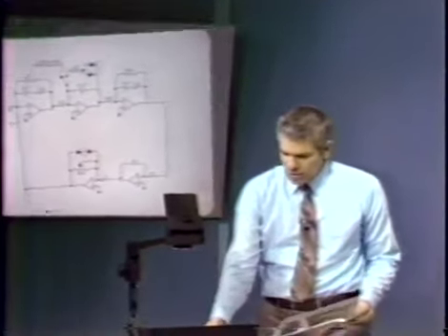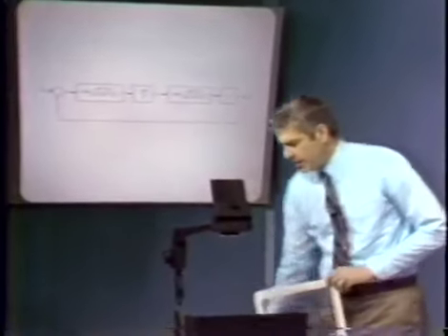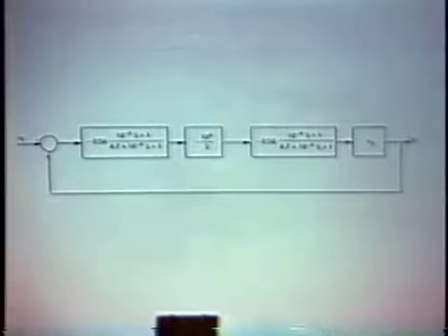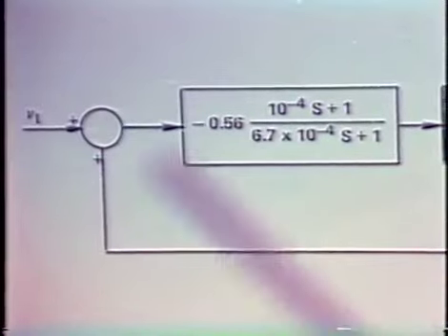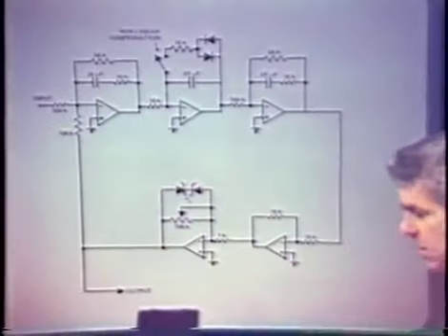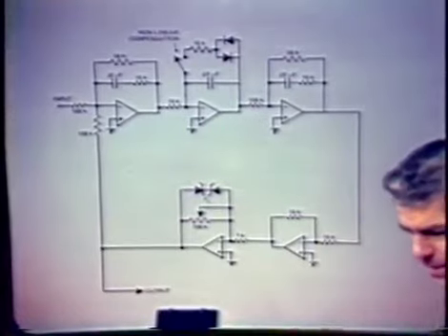There's a very nice one-to-one relationship between the block diagram and the circuit that I'd like to emphasize. Here's the input and the fed-back signal that are really summed, and we saw that earlier. The 2 input resistors here and here perform that summation.